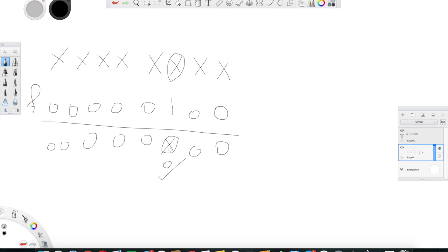So saying var ended with 0x04, this condition will be evaluated to true if this x is 1. However, I'm checking if this x is 0 or not, so I need to flip the condition. Okay? Or you can use the easy approach of equal 0x00. Both approaches work perfectly.